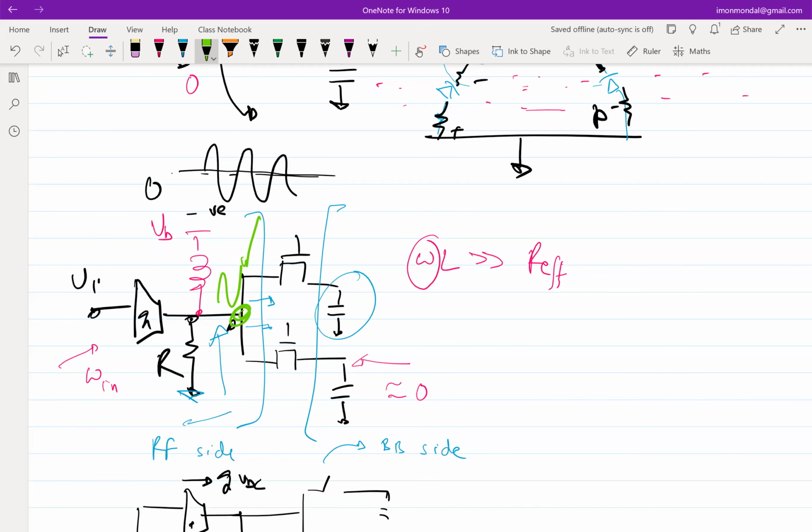When the signal goes above VDD, what can happen? So I am now drawing the switches only. So let's say this is biased approximately at VDD, maybe 0.9 VDD, maybe 0.8 VDD. I mean, don't assume it's VDD. But when the signal swings, this signal can go much higher than VDD. So what do you see as an issue with this? The switch has a problem, right?